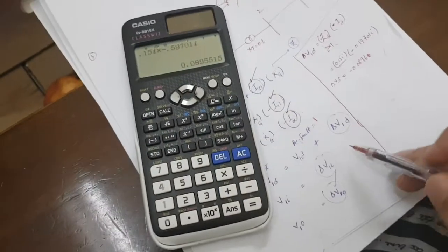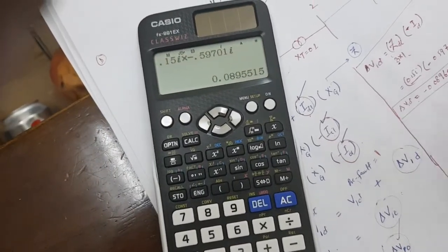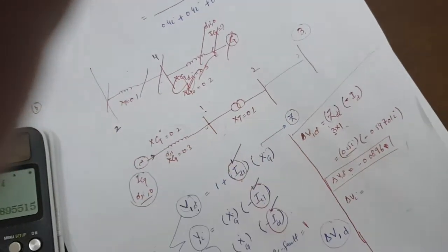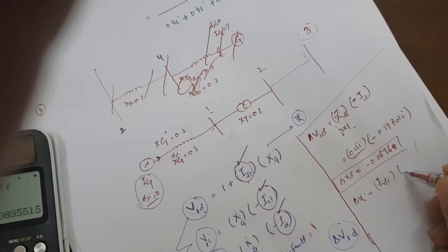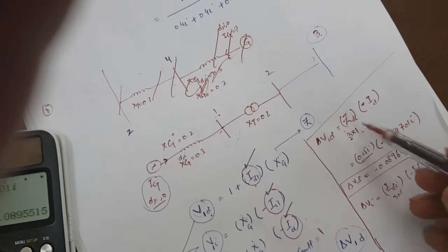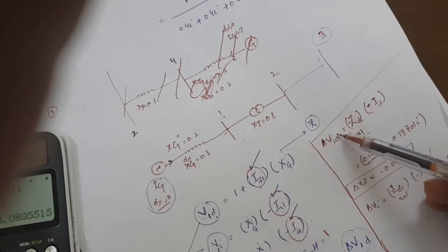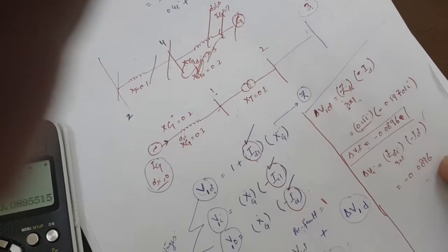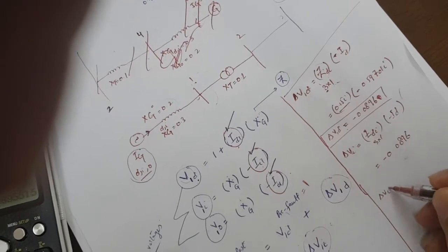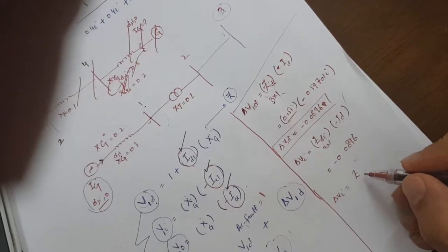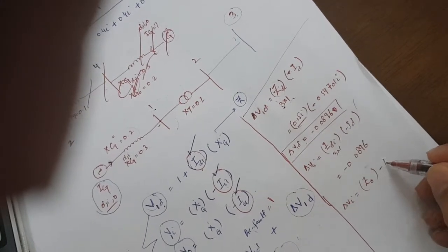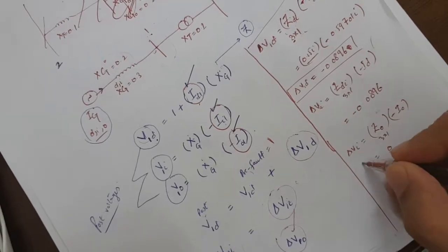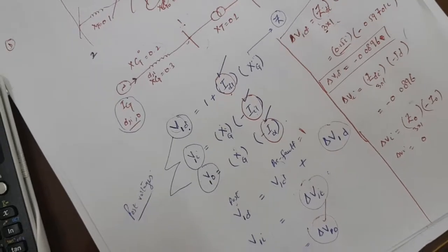So the second thing we have to find is delta Vi. The formula will be exactly the same, 3 cross 1, and the same values, because you can see in the question that for the positive and the negative sequence, the matrix is the same, so the value will be exactly the same. And for the zero sequence, we have a different Z matrix given in the question. 3 cross 1 is 0, so the whole value will be 0.